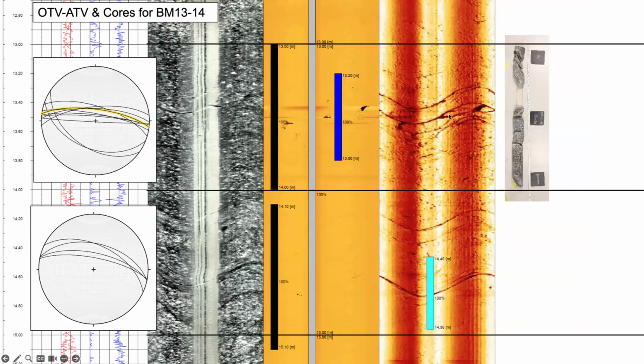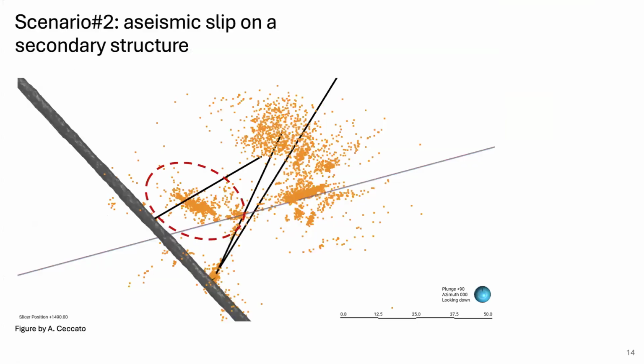They observed some existing fractures which have this orientation, shown here in the stereonet. And another coincidence is that later in the experiment, so the week after when we started to inject at high pressure, we actually activated a seismicity cluster which seemed to be placed on one of these structures, and these structures, such as the seismicity, of course, are clearly intersecting this borehole.